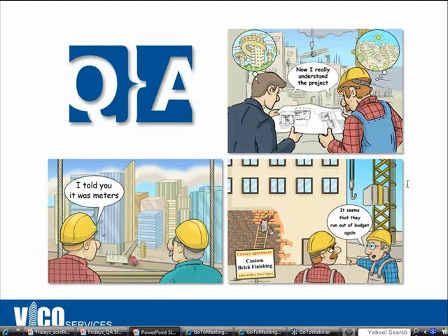Victor, here's a question for you. How do you incorporate cost information to each task in Vico Control? Yeah, there's just another field for the resources. So when I added the quantities, when I added those 40-hour estimates, it has a cost field. So every single quantity has a cost field with it that you can add and enter. And you can bring that in from an estimate manually, or you can bring that in from our 5D Vico software suite that directly connects with Control.